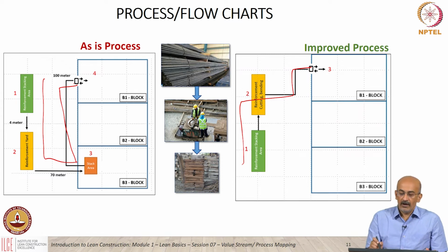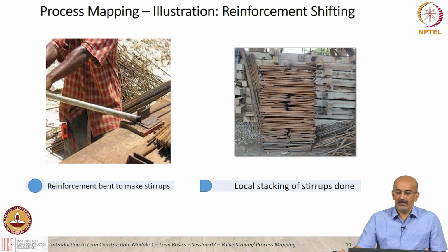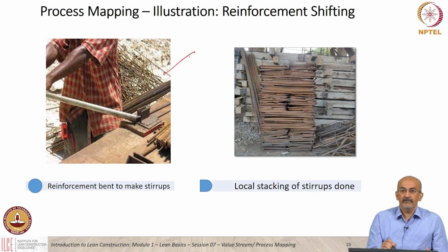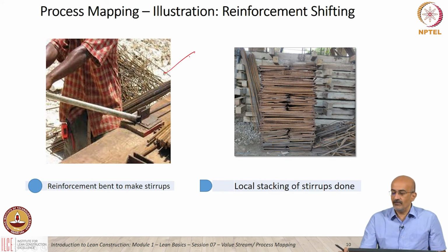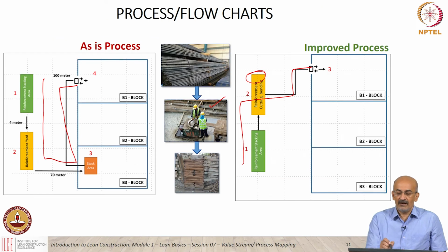And two, there is some amount of automation brought in the bending. If you notice, in the earlier case it was more manual, so this was probably why a bench was needed separately. Here, straightening, cutting and bending would be one bench where we could straighten, shift it, cut it, shift it, bend it, so that all of this takes place in one operation or in one location.